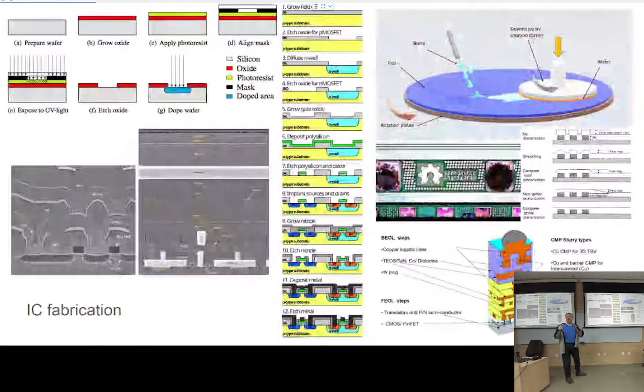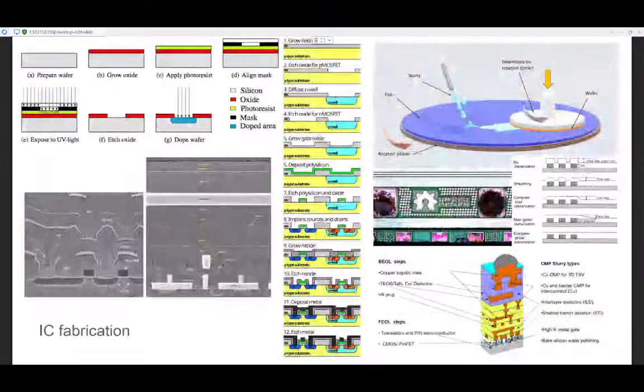Or I can have a particle accelerator and throw these charged particles at high speed, and they'll penetrate that. Then I have to heat it up because they'll ruin the silicon structure. So that's a single step. And here are the actual steps to making a CMOS circuit. So you start, then you create what we call the n-well. Then we put the drains and sources. This is actually one step, another step, combined. Then we deposit metal, aluminum. Then we etch the metal so that you only have the tracks left.